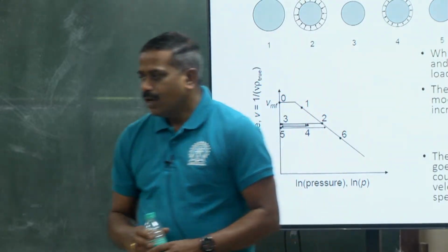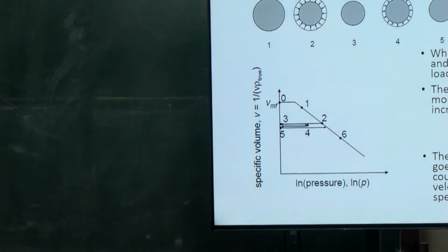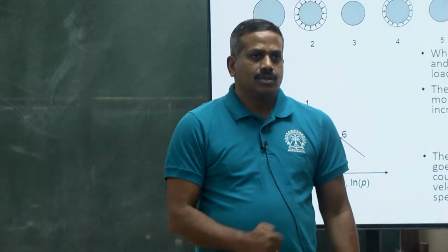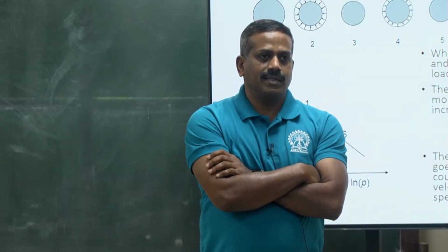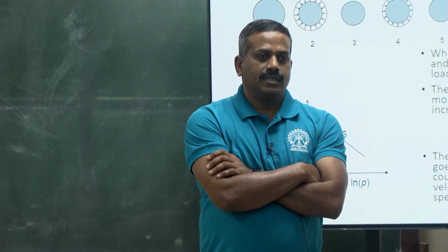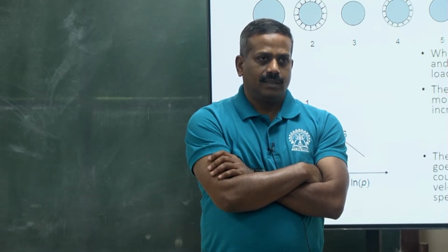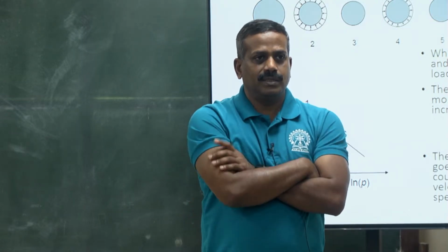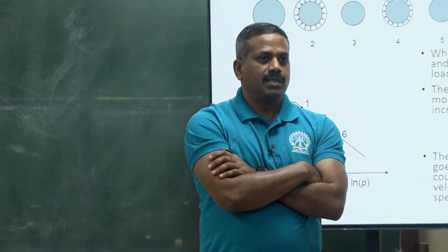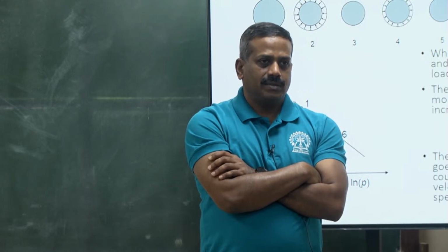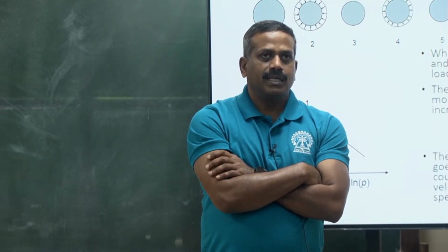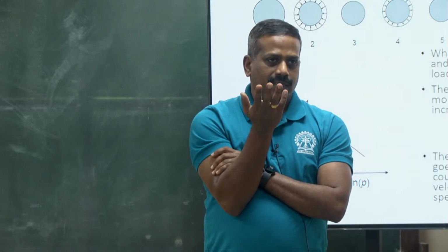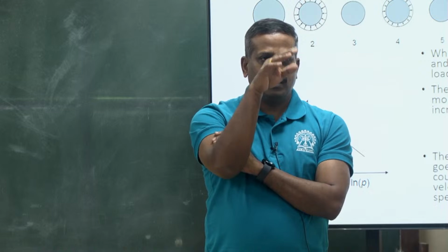So can we use this? Oh, okay. For that, more than aerated bulk density, your particle density will be much better. That will give a cleaner separation. For example, fiber particle density will be much different than protein particle density. So bulk density may not give a cleaner separation. I'm not sure if you remember that Geldart chart; they usually use particle density to classify fluidization behavior.